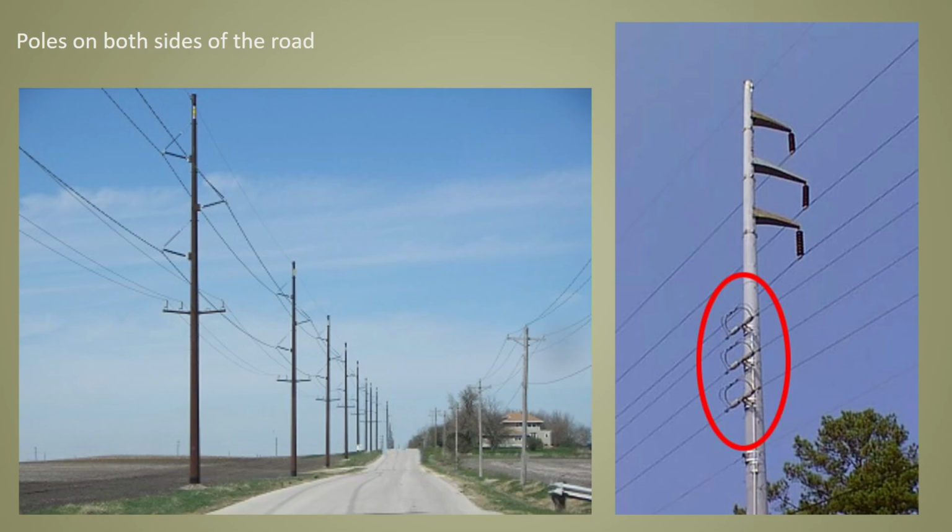So the reason this is important is most power pole owners do not want comms or communication attachers on their high power transmission lines. It's a safety hazard, and there are exceptions, but for the most part, we don't attach to poles that have transmission. One of the few exceptions is, like I said, that 69 to 115K. In those cases, they will often let communication companies attach to those poles.